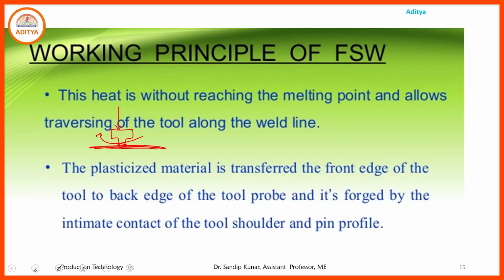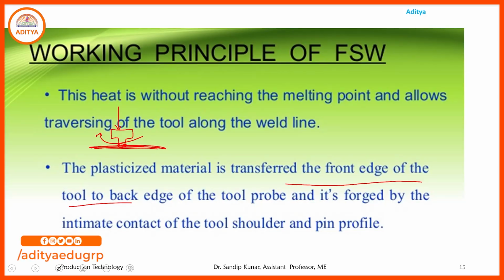And we are seeing that transfer from the front edge of the tool to the back edge of the tool probe, and it is forced by the intimate contact of the tool shoulder and pin profile. It means the friction takes place between the pin, meaning the probe surface, and the welding surface. Due to that contact surface, heat will be generated by mechanical friction, and a plastic state will be formed in those attached surfaces, which helps to join both plates.